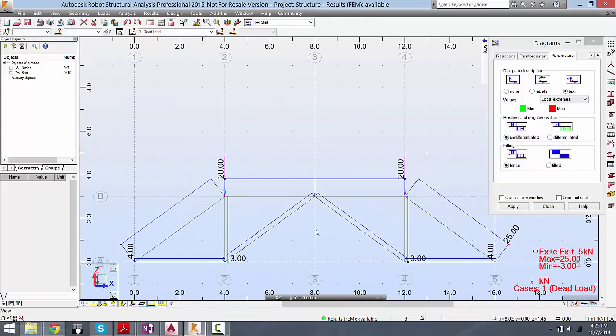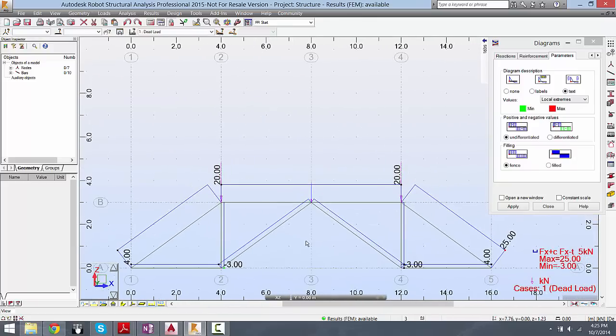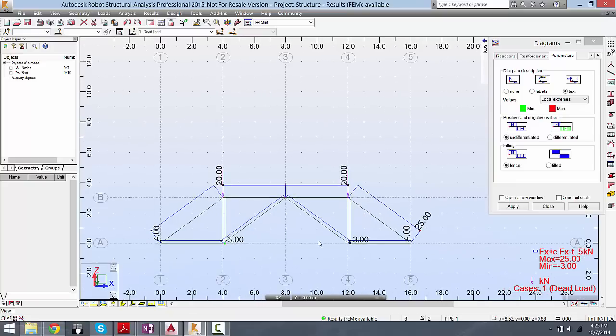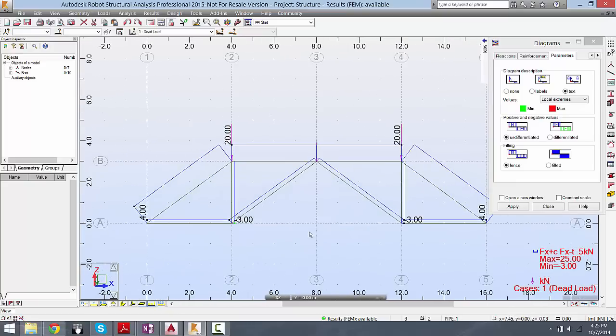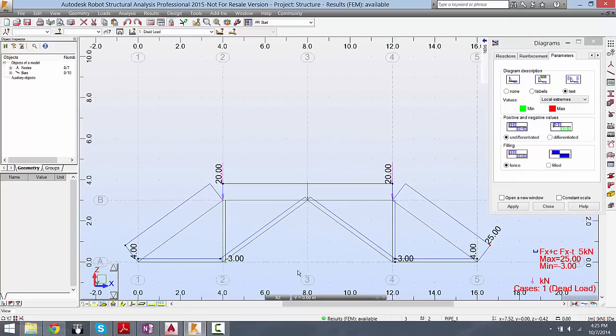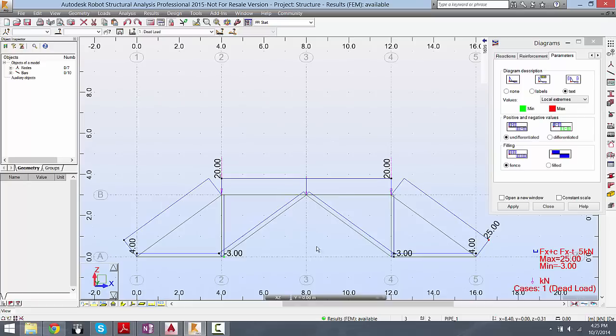And also the moments, if it bends concave up, then that is negative. This sign convention is different from what I'm accustomed to. I'm not sure what's the major thing. I know in the US most people like to have concave up mean positive moment. That would be the beam as a smiley face.